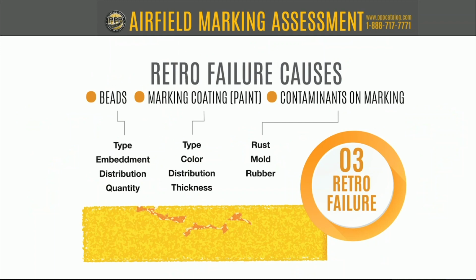We just went out and did this a couple days ago, actually. We did a test for Kentucky DOT at one of their airports that had algae growing from edge to edge of its runway, and it was essentially obscuring all of its white markings. We did a mobile assessment of all of those markings before, and then we had a contractor come in and do some water blasting with a light cleaning solution.